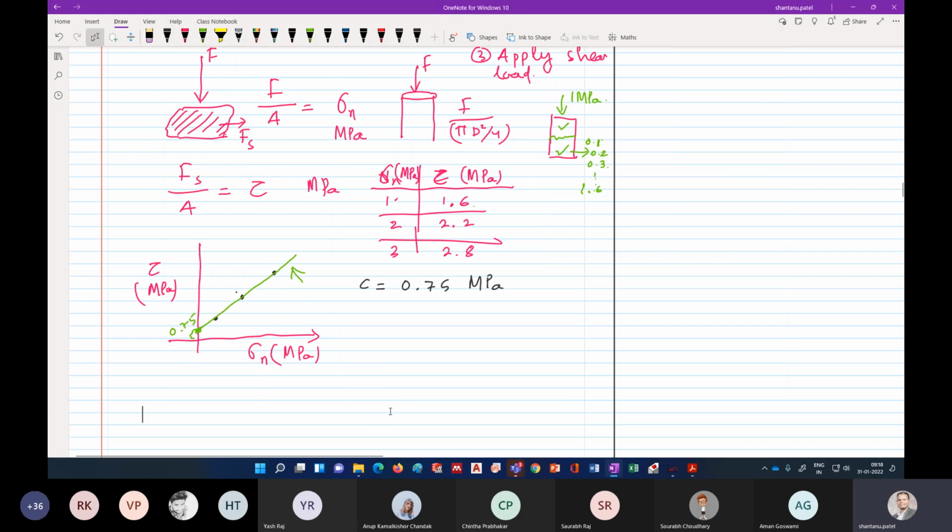So what is the friction angle here? How do you get the friction angle? I said that this y-intercept is your cohesion C, right? This distance, this to this. Right, what is the friction angle? Come on, you just studied 2 courses. So tan inverse of the slope of that line. Yes, the friction angle is the angle it makes with the x-axis, right? So this is your friction angle phi. Phi is maybe equal to, let's say, 43 degrees.